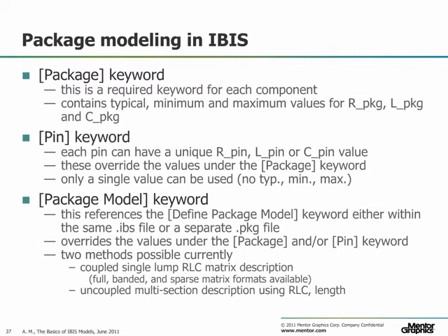The package model and define package model keywords can be used to make even more detailed package models. Because of its higher accuracy, if there is a package model keyword in the IBIS file, it will override the package information found under the pin or the package keywords.